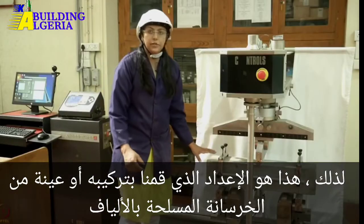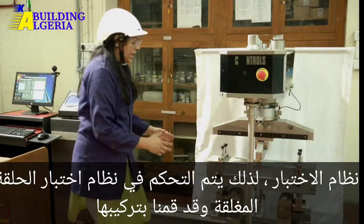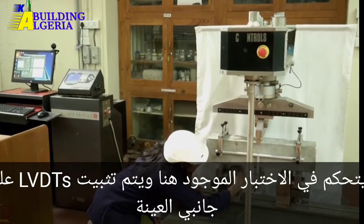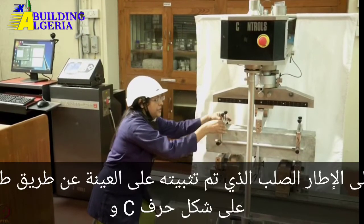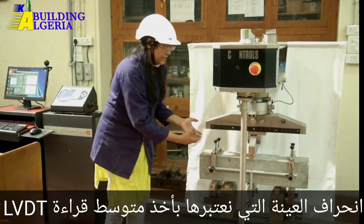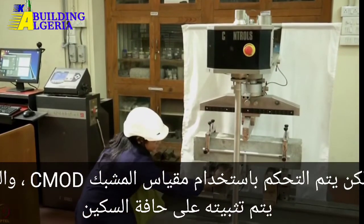This is the setup in which we have mounted our fiber reinforced concrete specimen onto the testing system. This is a controls closed loop testing system, and we have mounted here 3 sensors as I have explained before. That is the clip gauge with which we control the test, that is here, and LVDTs which are fixed on either side of the specimen onto the rigid frame, which is fixed to the specimen by means of a C-shaped collar. The deflection of the specimen we consider by taking an average of the readings of the 2 LVDTs on either side, but the control is done with the clip gauge CMOD, which is mounted onto the knife edge at the mid width.